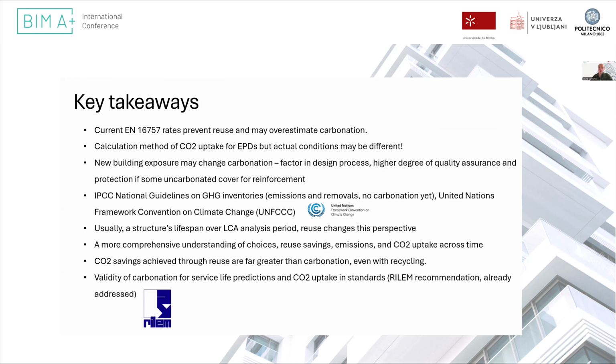This is also useful for LCA, because we usually take for granted in an LCA that the structure is there for 50 or 60 years. But if we are using reused elements, we perhaps need to incorporate a more comprehensive way to look at the fact that elements may have different lifespans, and match them, and be more considerate, especially when we are using them as structural components. And this is also addressing a RILEM recommendation that these carbonation rates need to be updated to be valid for service life and for CO2 uptake.